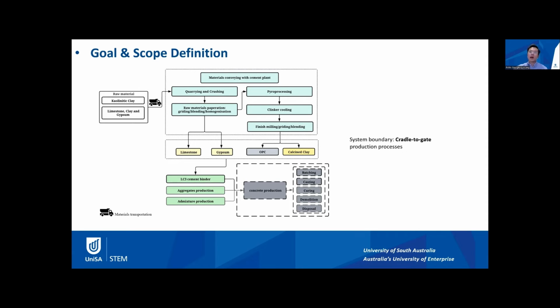In addition, unlike other byproducts from the industry, such as fly ash and slag, which can be obtained from the plant, calcined clay used in the LC3 requires thermal activation. This process is similar to Portland cement production, but the calcination temperature requirement is comparatively low.